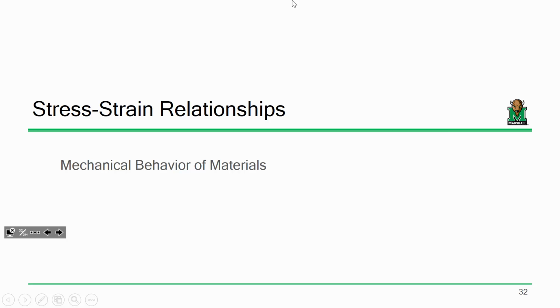I myself am strong enough to take this paper clip and permanently deform it, but I couldn't do that to that large metallic bar because, like we said, it wasn't the load that mattered, it was the stress and what have you. That still doesn't characterize aluminum. That still doesn't characterize copper. That still doesn't characterize concrete. Once you take the geometry out of the situation, so you start looking at things in terms of stress and strain, we can then go through and start to characterize the way these materials behave.